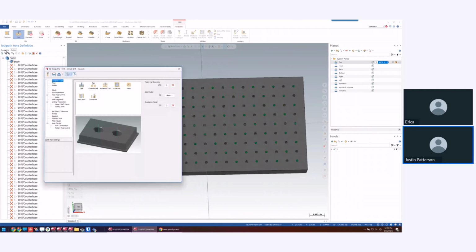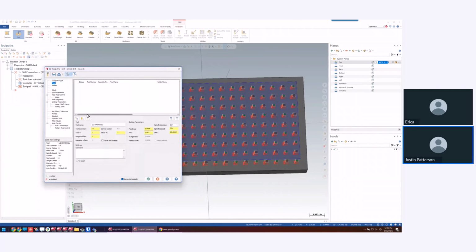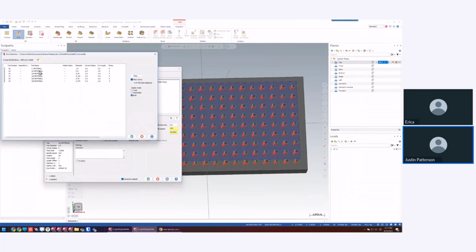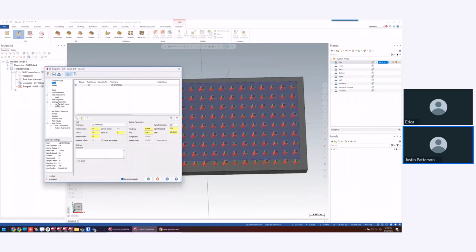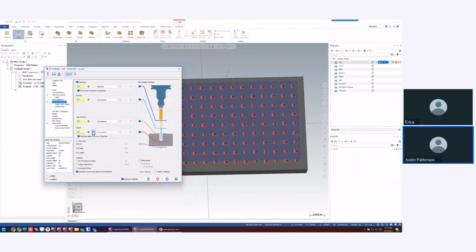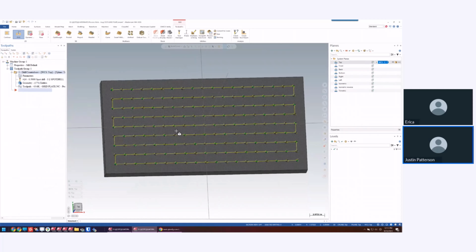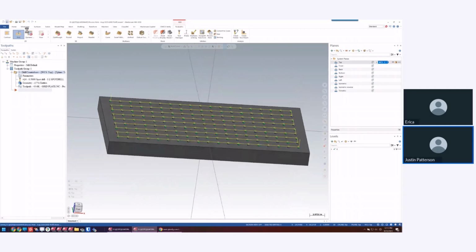So we go there. Again, go pick your spot drill. Take this 1/2-inch spot drill right here. Same fashion, calculate from the top. 1/2-inch is perfectly fine to me. That doesn't hurt nobody. Let's just use an incremental for now and make it 2, make it 2.5. Okay, looks good. So we went in there and we spot drilled all the holes. Now we can go with our process hole.